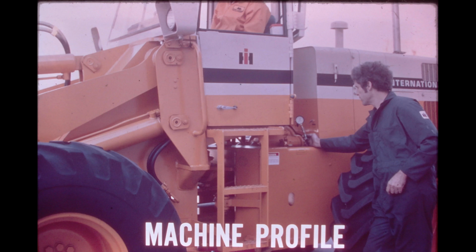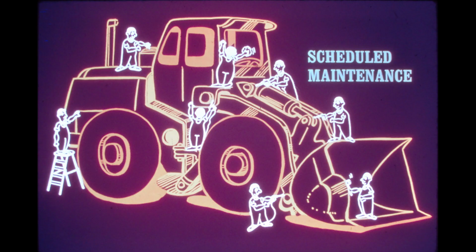One machine can differ from another and both be within specifications. A new machine should be tested when delivered. A record of initial pressure readings and engine stall speeds will help in interpreting readings taken at a time of trouble. Regular maintenance is one of the best ways to avoid problems in the operation of the payloader.